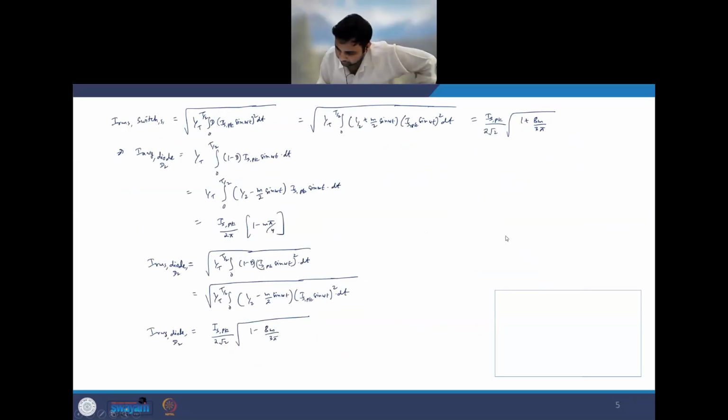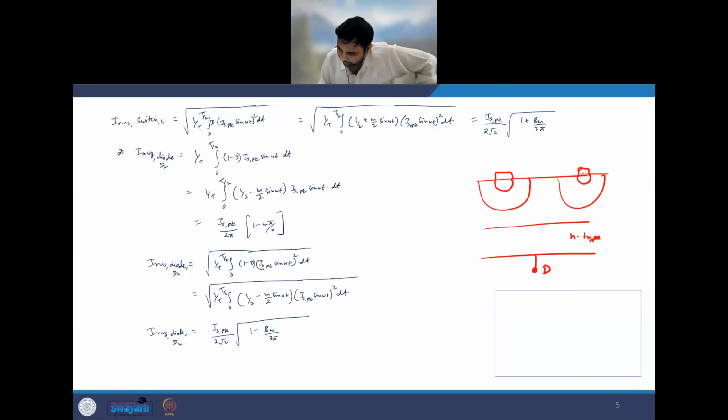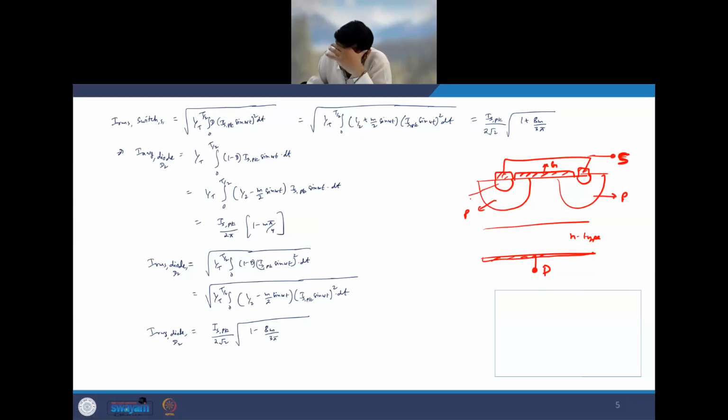And if you see the construction of any power MOSFET, this is your drain, this is your n type drift region, then here you have the p well, and then you have this n well, and this is nothing but your source terminal, not emitter, and this is your drain terminal, and your gate will be looking like this, obviously with gate G. So when you apply a positive potential between gate and source, what happens is that this P well which is there, this N which is there.